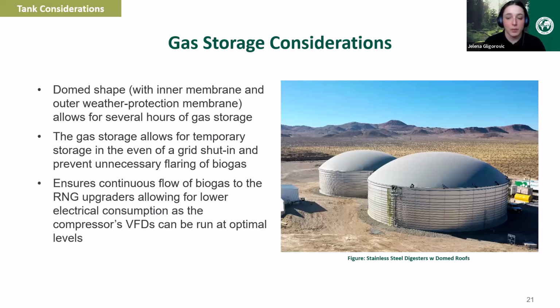The digesters can also be cleaned out and inspected by removing the roof. So the roof can be removed within a few hours, and it can be reinstalled within a day as well. They can be rolled back and lifted with a crane if you need complete entry into the tank, and if you need partial access, it can be folded in half to allow access to a particular side of the digester, for example, without removing the whole roof.